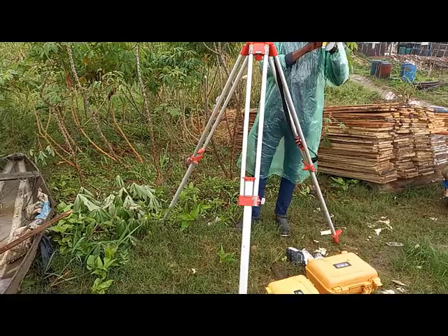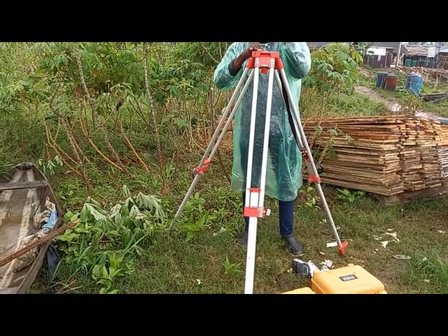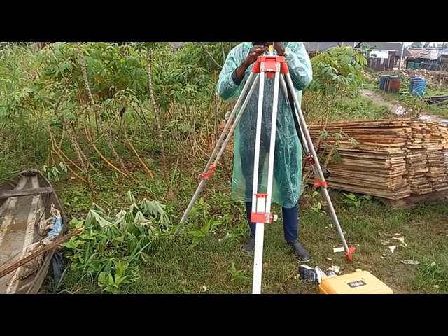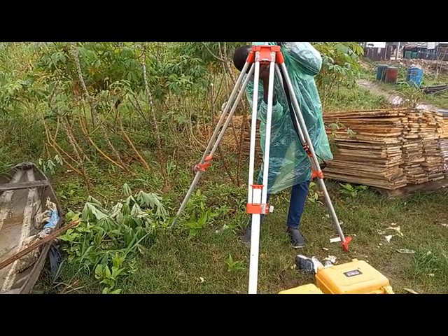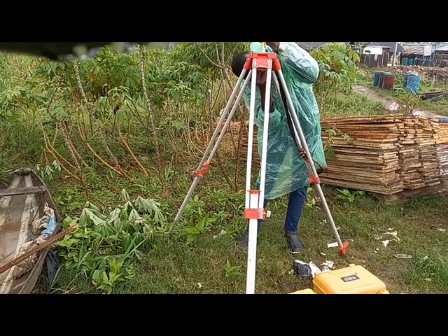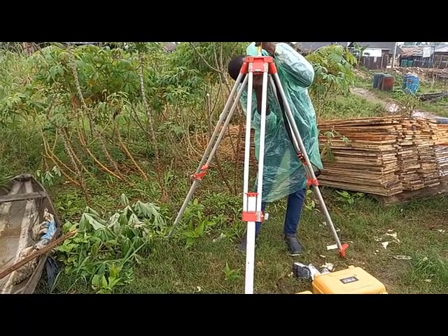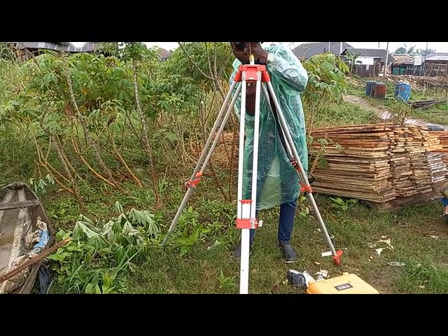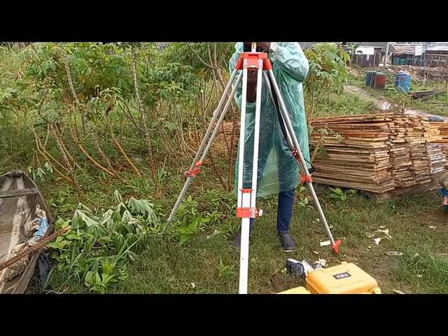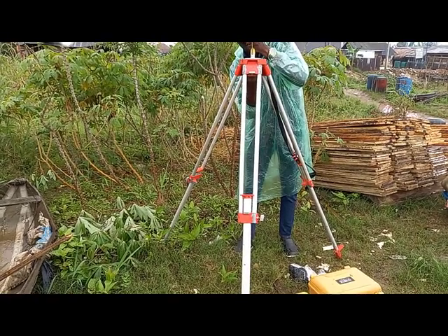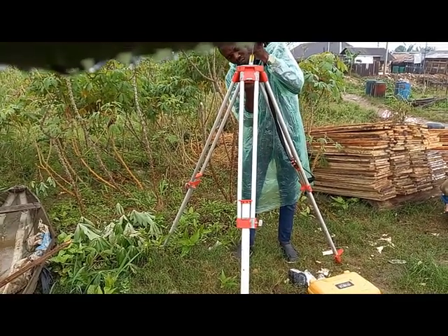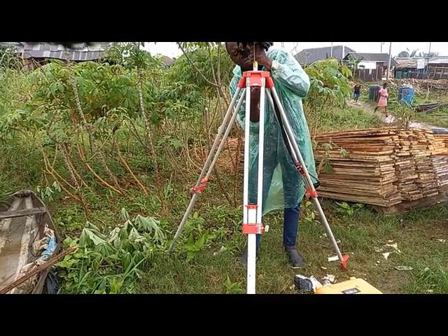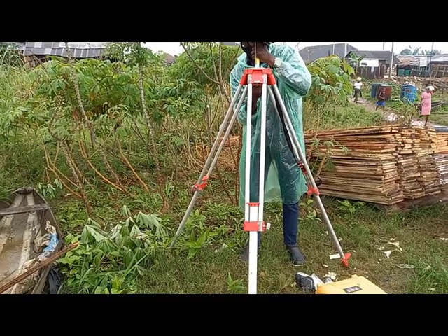There is a particular rod that I use to extend the GPS above the tripod. There is also an antenna for the GPS device. So you fix the battery, you fix the antenna for the GPS device, then you connect it to that rod and place it on top of the tripod. Because of the rain, you had to come with waterproof bags in order to protect the GPS devices.